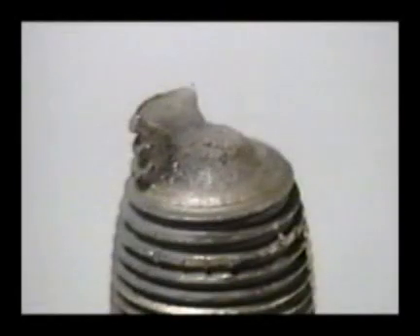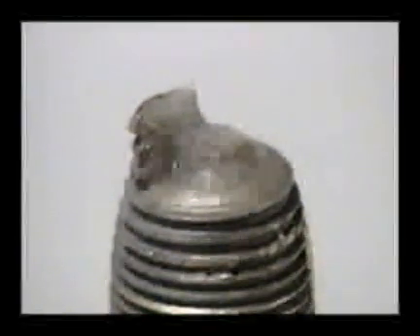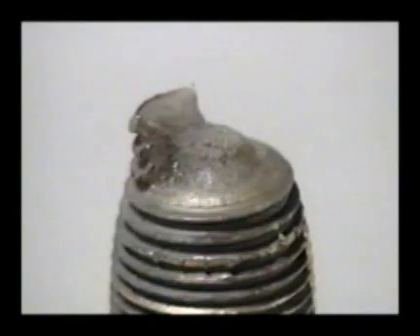Ductile fractures that are caused by tensile overloads produce rough, dark gray or black fractures with necking and a shear lip nearly all the way around the circumference. This cylinder bolt is an example of ductile fracture caused by tensile overload. Notice the rough texture, dark gray color, lack of reflection, necking, and shear lip. Under low magnification, we can see that the grains have stretched, pulling up into rows of peaks called tear ridges. It is these tear ridges that produce the dark gray color, as light is trapped in the valleys between them.